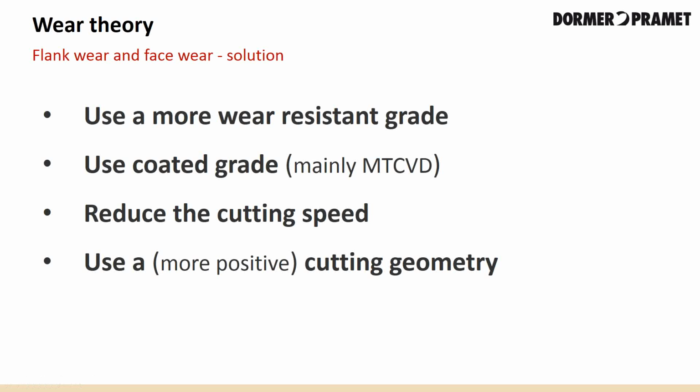So we can try to diminish this by using a more wear-resistant grade, or a coated grade, MTCVD. We can reduce the cutting speed or use a more positive cutting geometry.